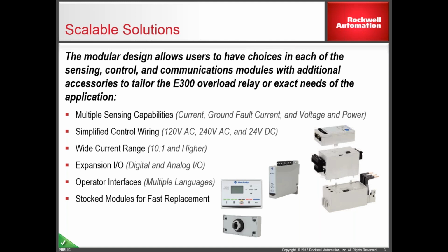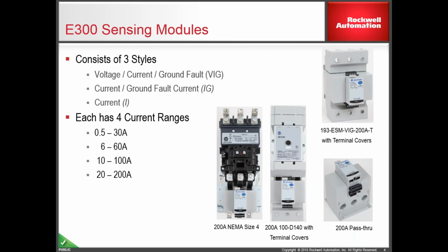This is the brains of it, and this is where all the I/O points get landed, where the output relays are located. And finally, on top piece of the sandwich, the bread, if you will, you have the communication module, and this is for the dual-port Ethernet. So you do need all 3 of these components to make up a functional overload relay. So even in a standalone application, you still need the COM module on the front.